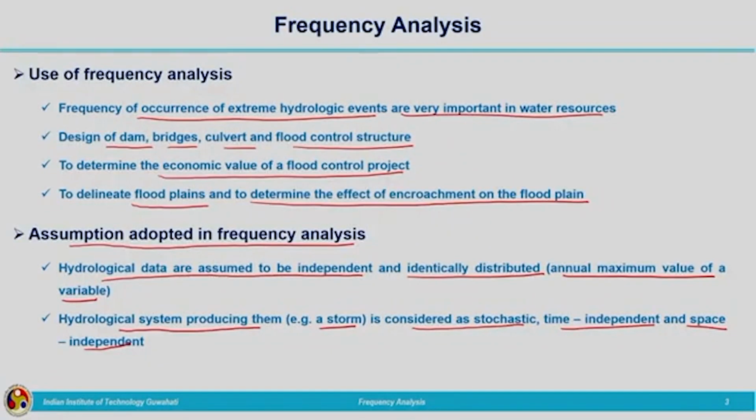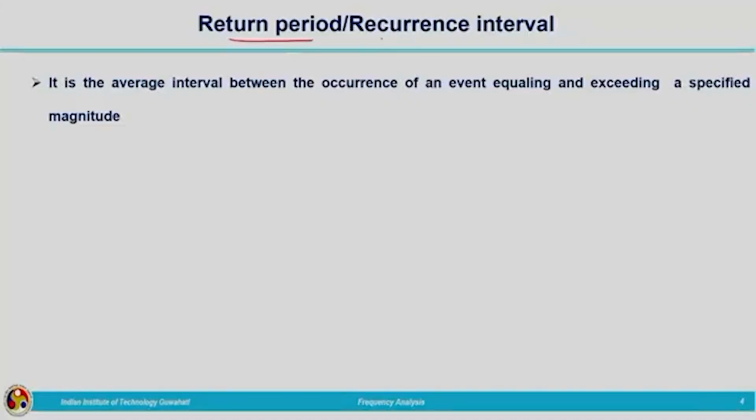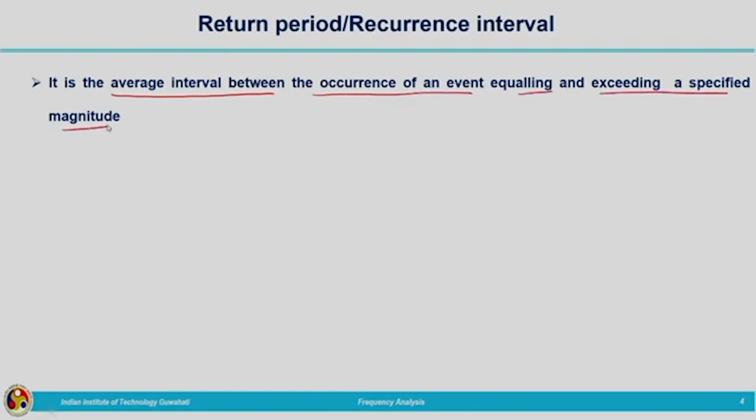Now, before going to the concepts related to frequency analysis, we need to understand an important term known as return period or recurrence interval. For this type of analysis, the most important terminology is the return period or recurrence interval. What is meant by this return period? It is the average interval between the occurrence of an event equaling or exceeding a specified magnitude.